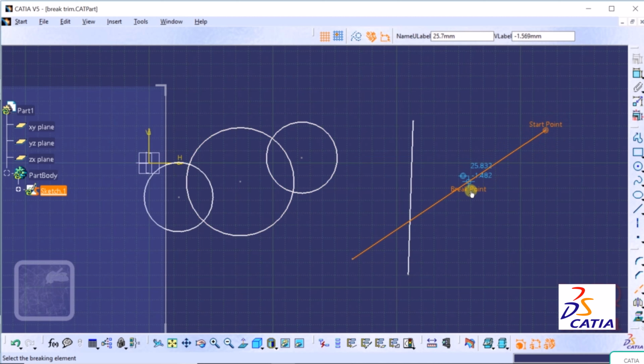And now we need to select the point from where we want to break this line. So I click here and we can also insert these values for the reference of point. I click here and then press escape to exit from the command. So when I take the mouse onto this line, we can see this left portion is selecting differently and then this right portion is selecting differently. I click somewhere outside. So in this way we can break the line.